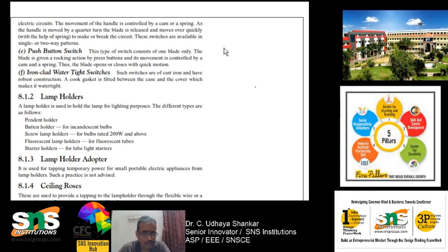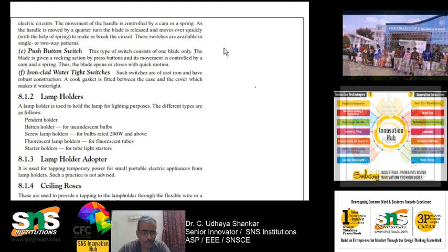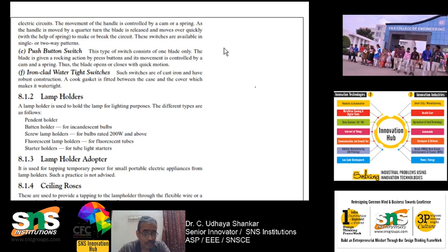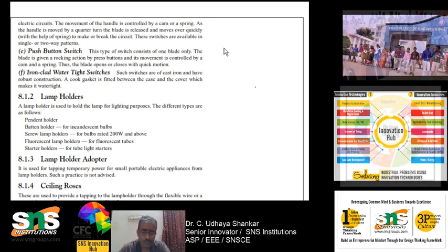It is controlled by means of a cam or spring. The handle is moved by a quarter turn by the blade, and it is released and moves over quickly. These switches are also available in single as well as two-way patterns.